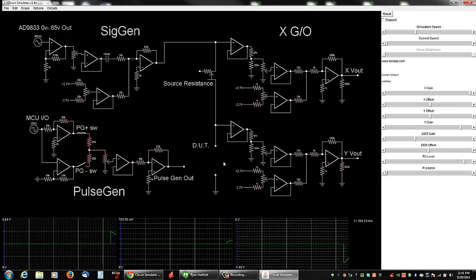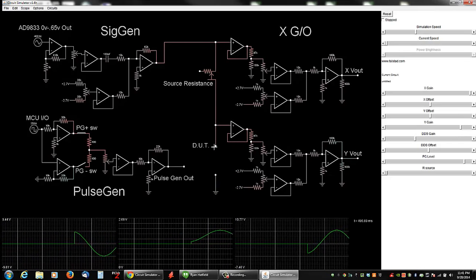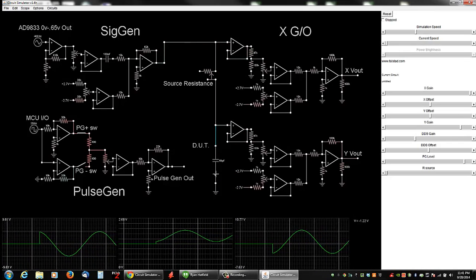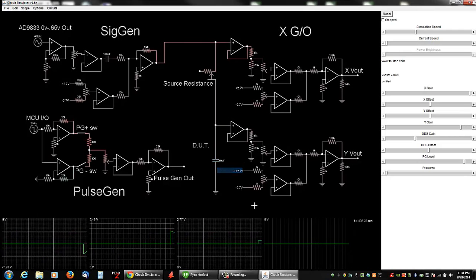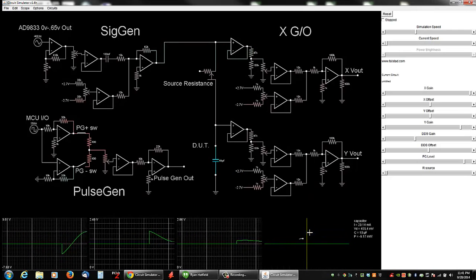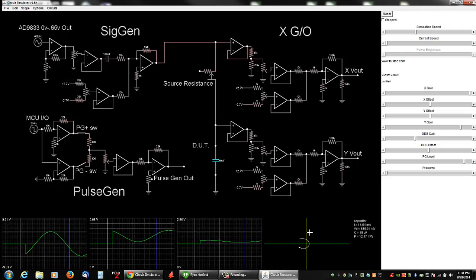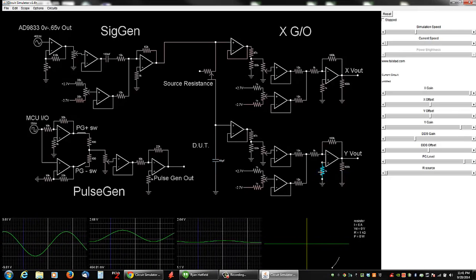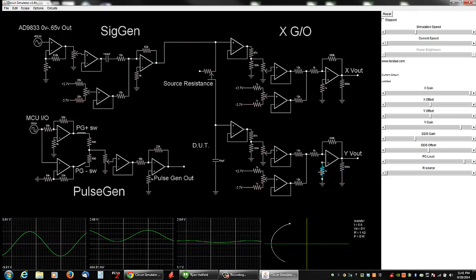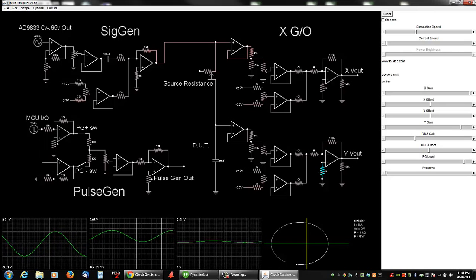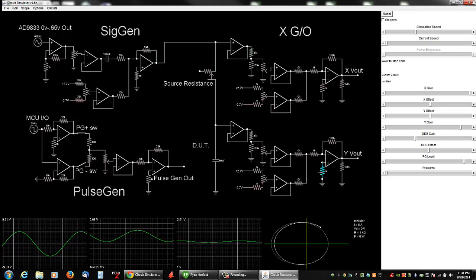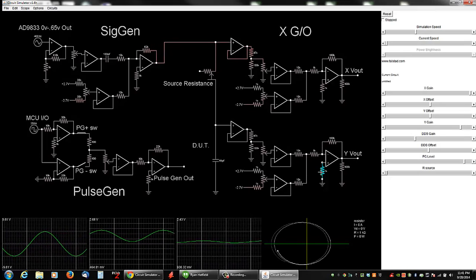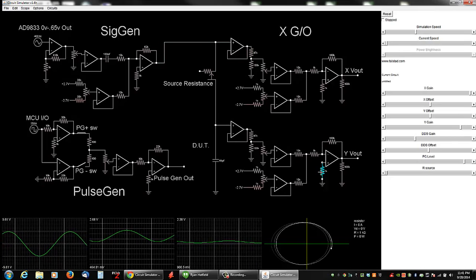If I get rid of that and throw a capacitor in there, view that in the scope, then change all these goofy settings. It's got to steady out. It's got to get to a steady state here. And again, here's where the scaling gets a little goofy. You see it rescaling itself there. And you see how it's overshooting and kind of undershooting, and that's the AC coupling going on.